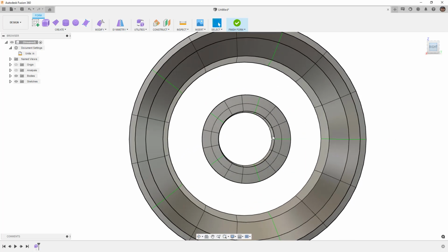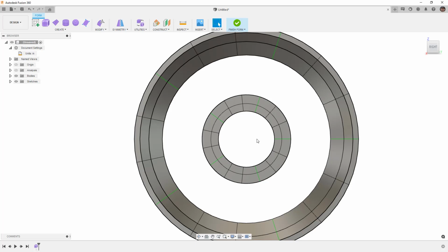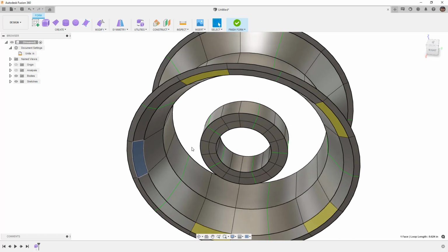Now, when we think about the way in which rims are made, certain features like the lug holes, those are really best added later on. We would need way too many edges to control those details. So we're not going to worry about those. We only want to worry about connecting the spokes from this outer ring to this inner ring. And when we do that, we can think about things like whether or not we want a crease here. We're going from a creased edge to a creased edge, but we might not want that to be the case.